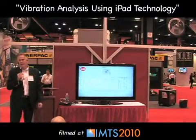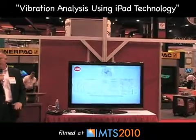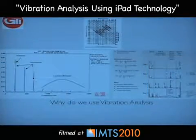Do we use vibration analysis and what is it all about? Vibration analysis has been used for many, many years in the machine tool industry. Moving components break down. What way can we take information from the vibration that comes out of these units as they're rotating and moving and be able to find out when they're going to fail? When we know a machine is going to fail, we can procure parts, we can have the bearings ahead of time. We're able to make sure that downtime is cut down to a minimum.